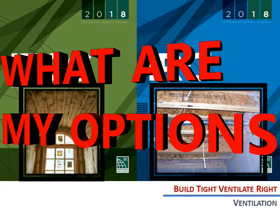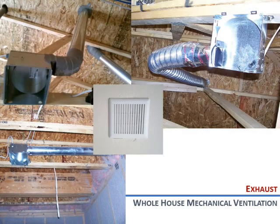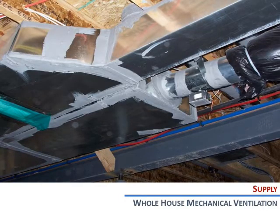Oh, I'm certainly glad you asked. The code allows for 3 different ventilation strategies. The first being exhaust only. This could be a dedicated bathroom or laundry room exhaust fan. The second is supply only. This is where ductwork brings in outside air into a furnace's return air plenum.